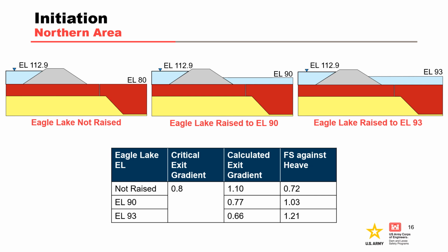In May 2011, it became apparent that the water elevation in Steel Bayou, and thus the maximum water elevation that would be achievable in Eagle Lake, would be no greater than elevation 90. It was therefore concluded that a raise of the Eagle Lake water surface alone would be questionably sufficient to resist seepage pressures. Based on the results of the analysis, it was determined that the construction of the emergency berm was also necessary, but the analysis was not expanded to include the berm in the calculations.